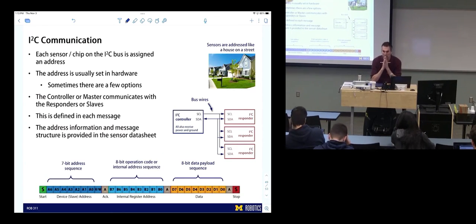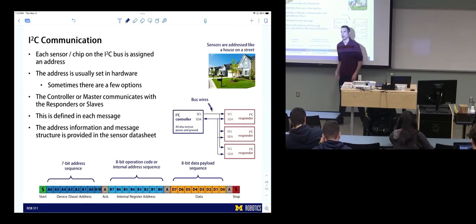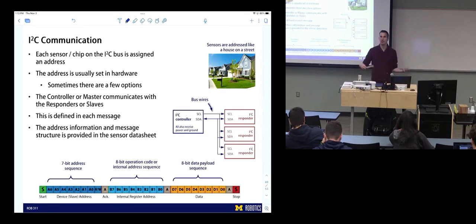I2C is addressed by what? Like, how do you know which chip is being talked to? The address, as an actual address. I told you it was 8 bits, but I think it's actually 7 bits, because the last bit is used, I think, to tell the system whether it's reading or writing. The purpose of that message is to read or to write.